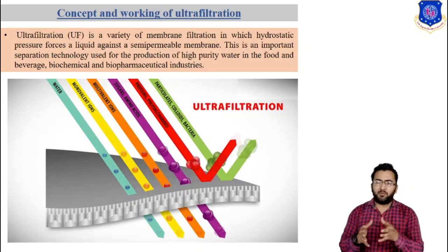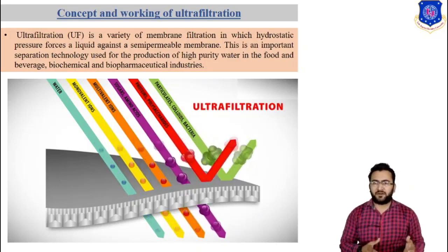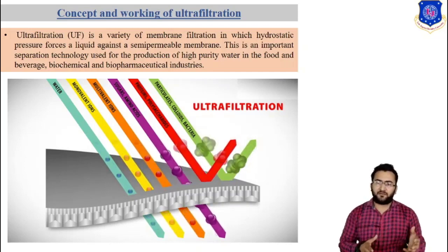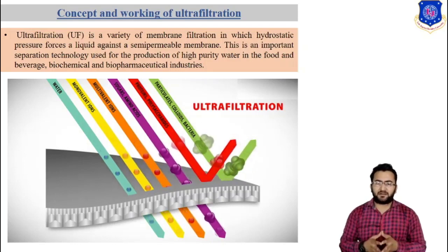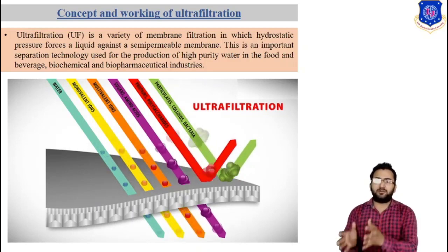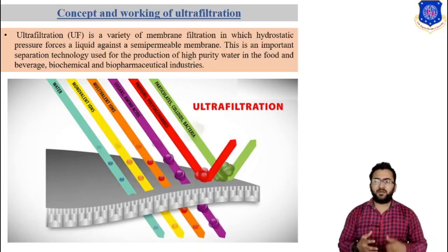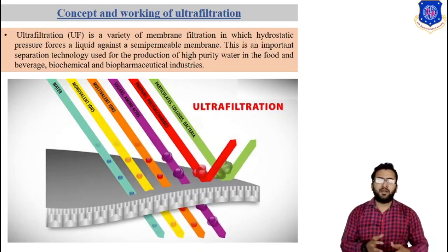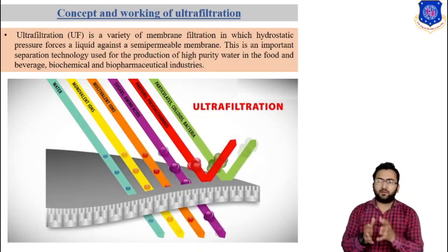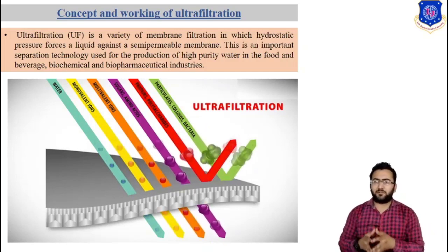Since only high molecular weight species are removed in ultrafiltration, the osmotic pressure difference across the membrane surface is negligible. Low applied pressures are therefore sufficient to achieve a high flux rate. Ultrafiltration uses a tangential flow design to reduce solute accumulation at the membrane surface. A tangential flow ultrafiltration device may be a spiral wound cartridge containing several square feet of membrane wrapped onto a center core tube, or a hollow fiber cartridge containing dozens of thin ultrafiltration membrane fibers.